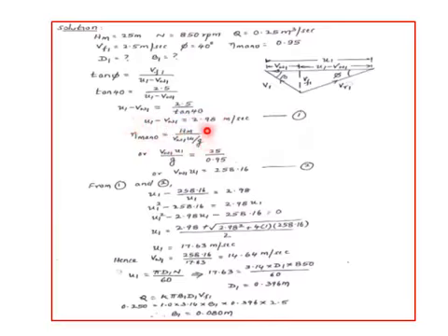Now you can make use of manometric efficiency, which is Hm by work done per unit weight of water. Since these two quantities are again not known, Vw1 u1 by g can be written as 25 divided by the manometric efficiency. Multiplying by g, you get Vw1 u1 as 258.16. So you take Vw1 as 258.16 by u1 and substitute in this equation: u1 minus 258.16 divided by u1 equals 2.98. You get a quadratic equation, and you can solve it to get the value of u1.